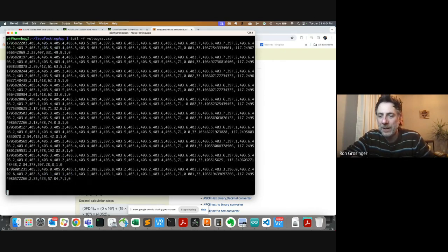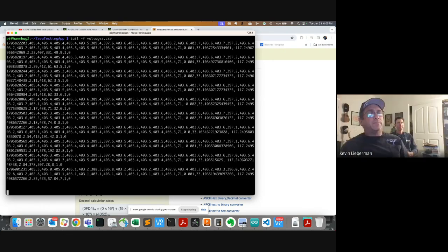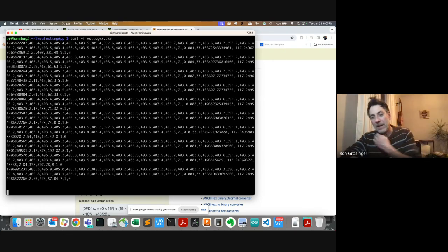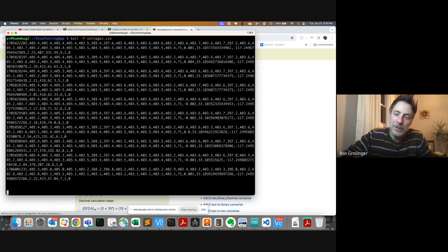I think data acquisition would be great because, besides just the BMS, if you have an issue, where on the road did you have the issue? Were you climbing a hill? Were you charging? Where were you? How long were you driving for? Which component do you think failed? That would be great to log. And then you could learn over time as you do these conversions which components are more reliable for what you're doing. So this is great stuff you're doing.